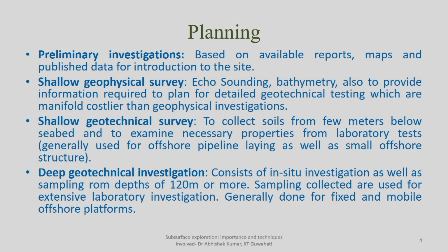So, when we go for planning of any geotechnical investigation, first of all we have to go with preliminary investigation, which starts with exploring the available reports, which talk about maybe the soil type, topographical information, geological information, geomorphological information, or maybe some kind of challenges, some forensic investigation done at the proposed site or its environment or adjoining sites in the past.